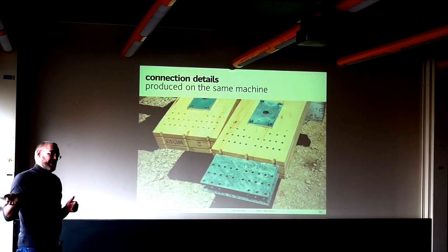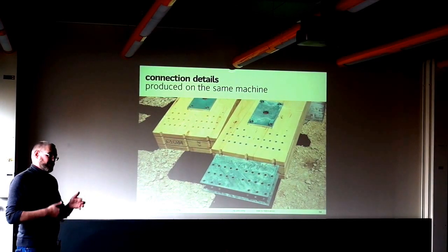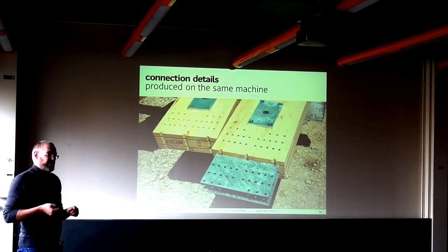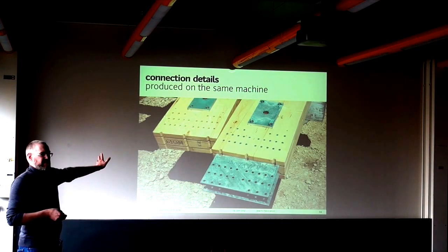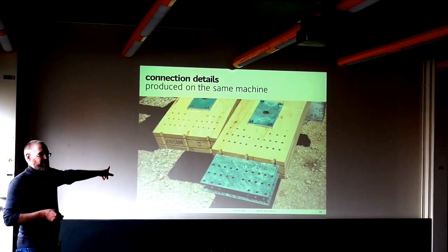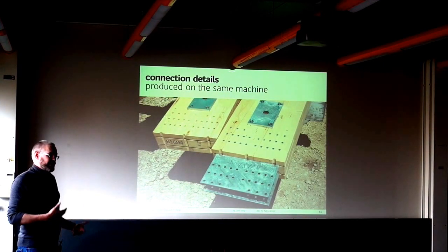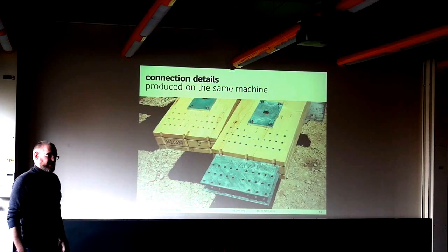And then you basically go backwards from the assembly sequence that is needed, for whatever reason, until the ordering of the raw material, to get the sequencing right. There are very few places where you can store. I think in the end it was net about 1,000 cubic meters of timber. So you have to work in the right schedule and fabricate just in time for the assembly.